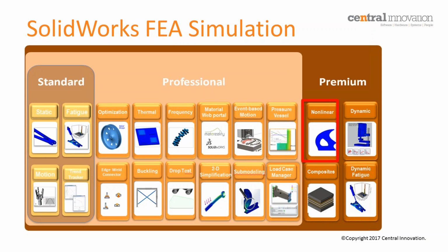Specifically today, we are focusing on nonlinearities. However, on top, you can do dynamic loads, nonlinear and dynamic at the same time. We also have dynamic fatigue analysis, and there is a possibility to look at composites with multi-layer material stacking on top of each other.